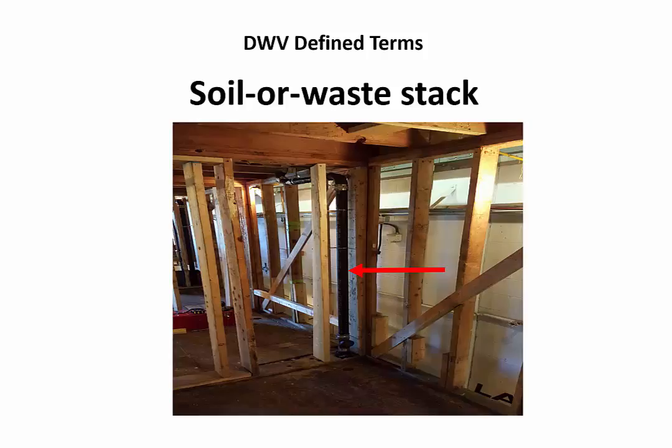Stacks drain to branches or sanitary building drains at their base, and the base of every stack requires a cleanout as per Article 24.7.1, Sentence 7. Soil or waste stacks are sized in accordance with Table 24.10.6a.